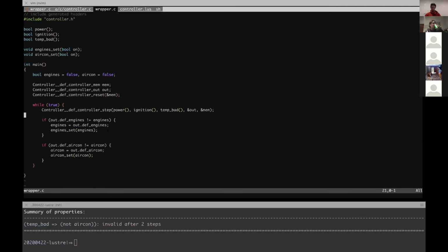when I was writing state machines in C code, where you write a generic transition function, a generic output function, and then parameterize them with a transition table and an output table? Right. And I mean, if you wrapped your two if statements here into a function that was driven by a table, an output table that took a state and performed the appropriate on or off function calls, you would have something very similar to what I would have written by hand.